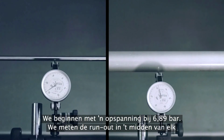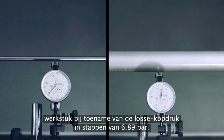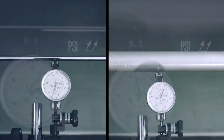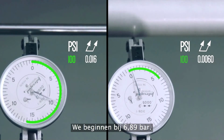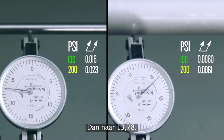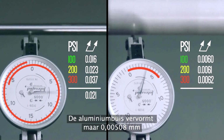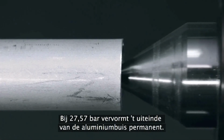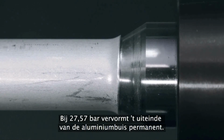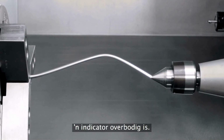Starting with the parts held at 100 psi, we'll measure runout at the middle of each part as we make 100 psi tailstock pressure increases. Okay, starting at 100 psi, increasing to 200, and then 300, the steel rod deforms significantly by an additional 21 thou. Its neighbor, the aluminum tube, deforms by only 2/10. All the way up to 400 psi, the end of the aluminum tube permanently deforms. Meanwhile, at 400 psi, the steel rod bends so much we don't need an indicator anymore.